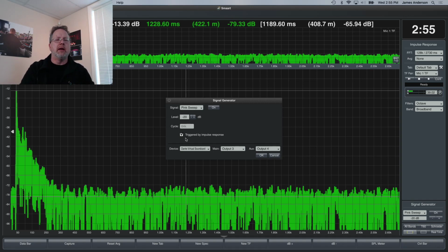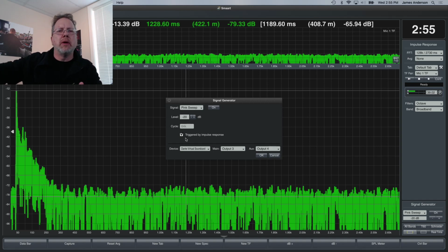And so that's why we average our measurement. But one of the cool side effects when you're putting in the exact same signal every single time is that it's much more, as they say, deterministic. What's really going to be interesting here, I think we're going to see this, is that a weird thing happens. When I put in 1K, I get out 1K, 39 milliseconds later. I put in 2K, I get 2K out 39 milliseconds later. But I also got 2K out when I put in 1K.